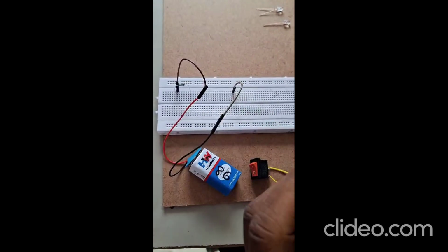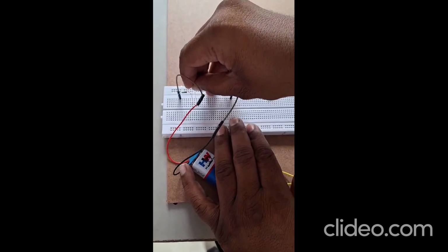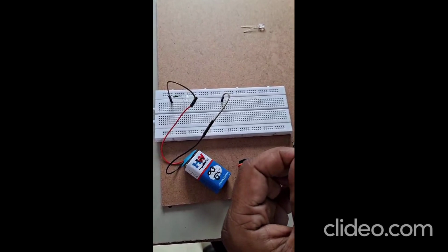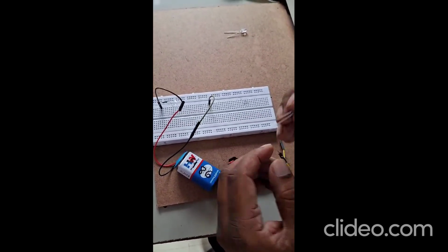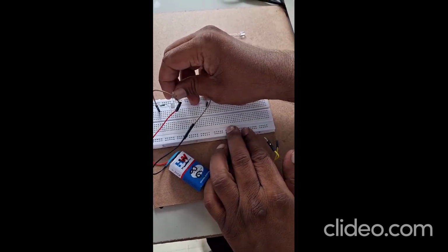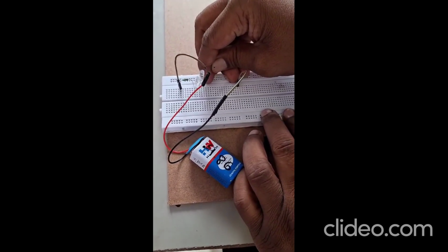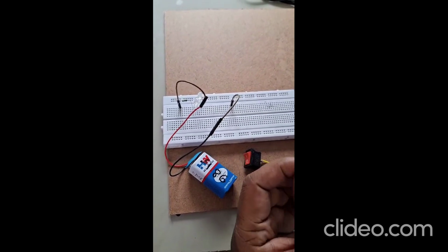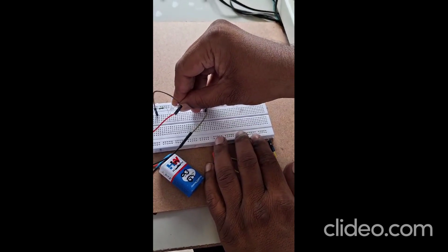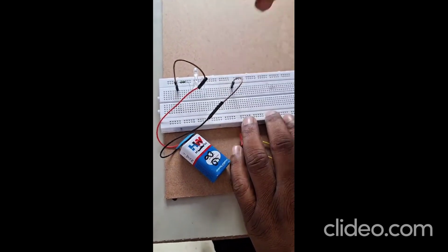Next is the LED. Positive is there. So first we have to connect the positive with the resistor, and negative in any other column. Next, the second LED, since we are planning to connect 3 LEDs in series, so there was a negative connection here. On that negative I have to connect the positive of the LED, in that same column. The negative I am connecting somewhere else in any other column. Next, one more LED. To the last negative I am connecting the positive of the next LED, and the last LED's negative I am connecting somewhere else.